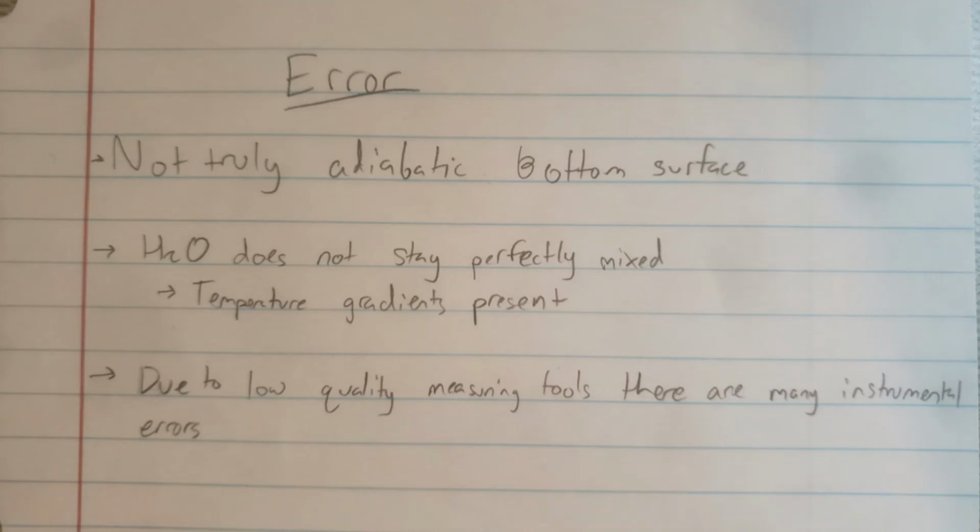So in the end, based on my analysis of the error, I believe the calculated convection coefficient of 55.88 is going to be too high, or greater than the expected value, mainly due to the heating from the bottom reducing the total time and therefore increasing the calculated convection coefficient. With further refinement and more precision, this could be a very valid experiment for measuring the convection coefficient as a result of a fan blowing air.